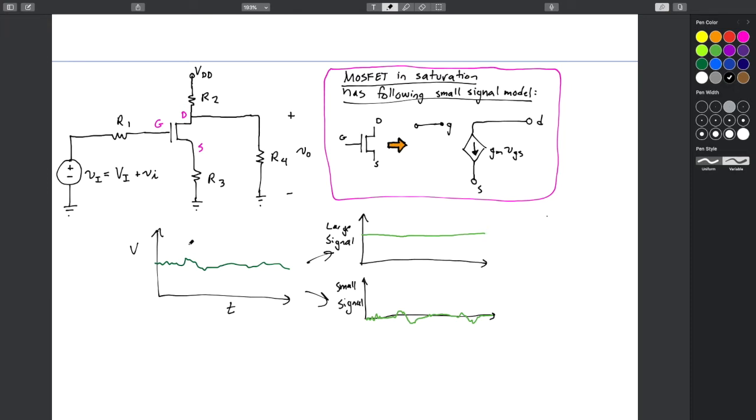And that means, and again, refer to lecture notes or especially the textbook for the detailed support of that, it's based around the idea that, in terms of voltages and currents, you might have a voltage signal that looks like this right here. It's at some value and it's going up and down. What we can do is break it down into two pieces, one of which is the large signal value, right here, and the other of which is the small signal value.